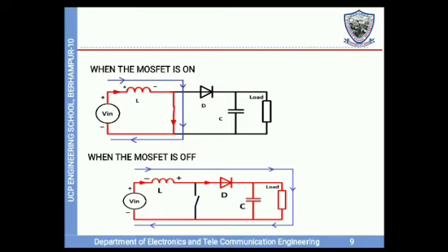The slow rise in current is due to the inductor converting the current into a magnetic field around it. Once the magnetic field is fully built around it, there will be no opposition in the current flow. When the inductor has built sufficient magnetic field around it, in the above shown electrical polarity, the MOSFET will be turned off.